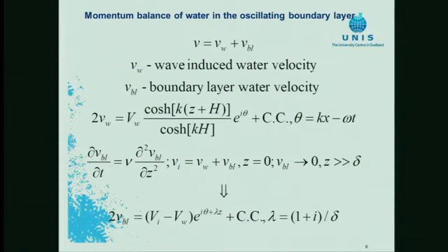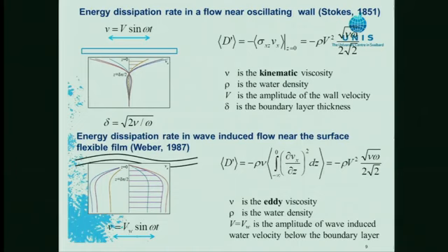So then in this situation, we have this equation describing boundary layer velocity with boundary conditions specified at the boundaries of the layer. And the solution is very simple. So then here we have the boundary layer thickness. It was introduced before. This solution is just an extension of the classical Stokes problem about an oscillating plate. In our case, if we had a fixed flat plate, not drifting, not moving, then we have below the plate an oscillating velocity field due to the penetrating wave, and below the plate we have a boundary layer.